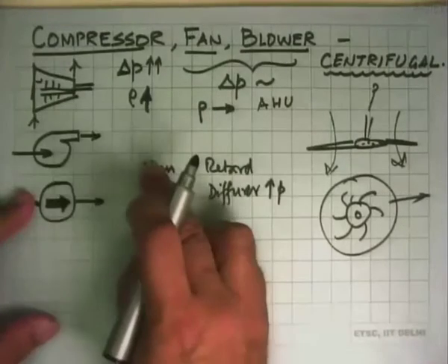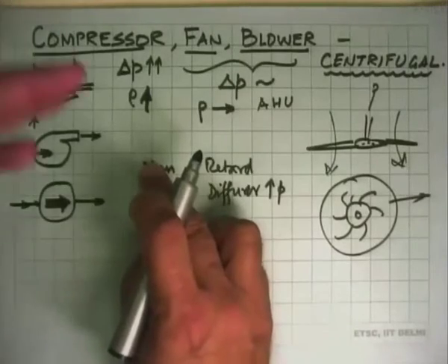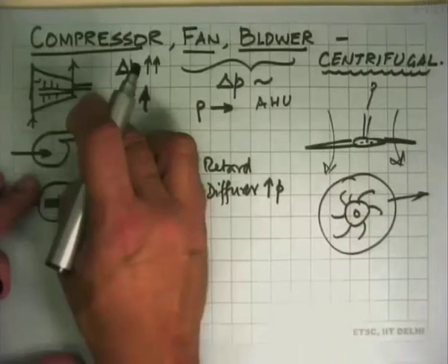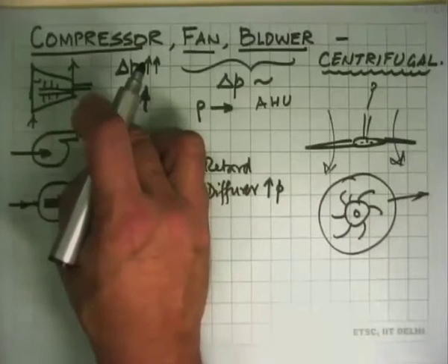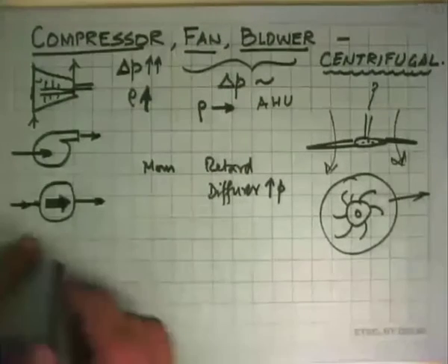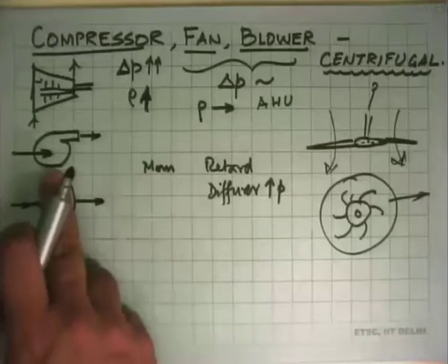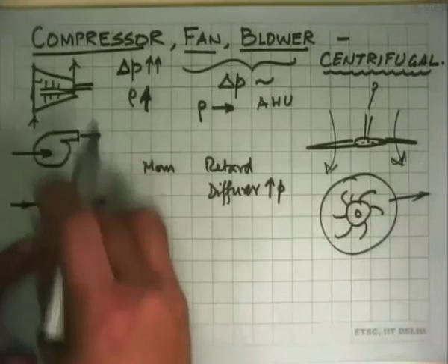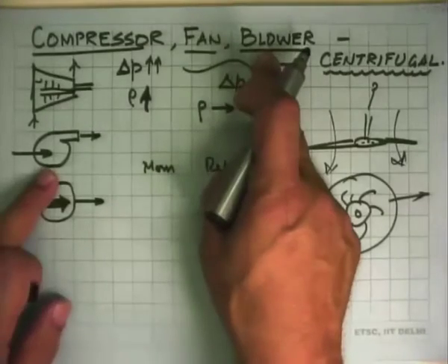And then we can again put it into the next set of blades, do the same thing, and do the same thing here, then again. So this would be called multi-stage compressors, and all practical compressors by and large are multi-stage. The aircraft engine is a good example of that. In schematics, we can also use this symbol, sometimes for compressors, but largely for fans and blowers, these symbols.